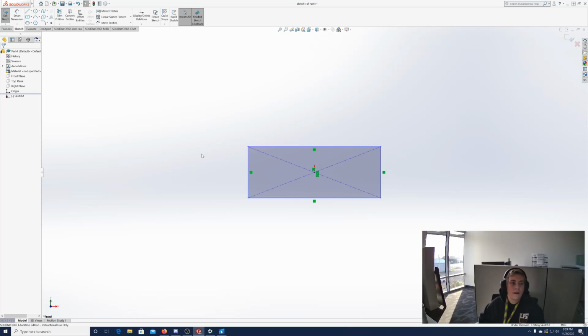With assemblies, you do have to have it fully defined in terms of how the parts fit together. If you have two parts, you have to mate them a certain way when you assemble them. Say you have a ball and a socket, right? You can mate the ball with the socket, but you don't necessarily define which direction the ball is facing, so it can still rotate within the socket. So that's not technically fully defined.